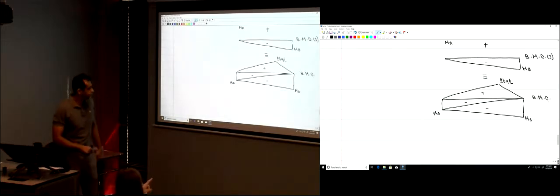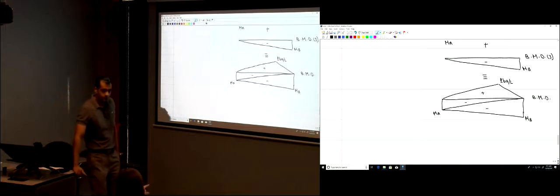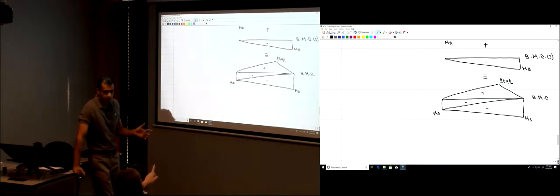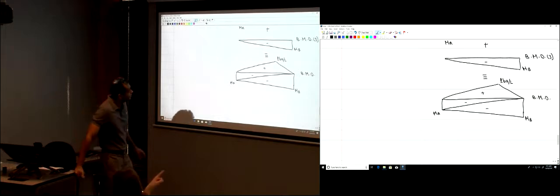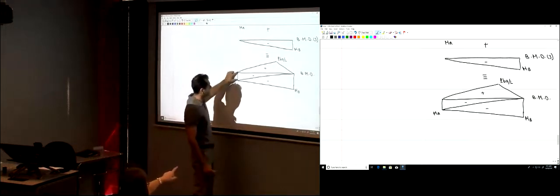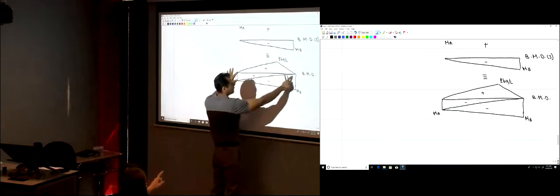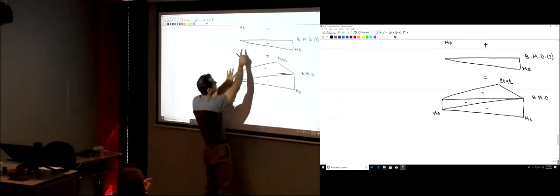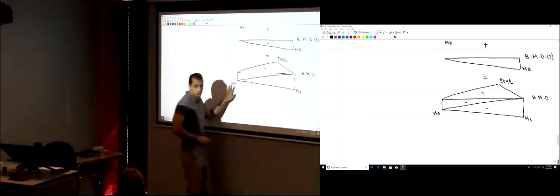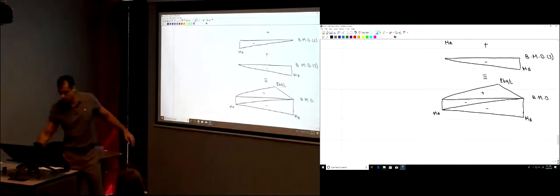So the tip for B would go to the 0 or just go to the bottom of A? Is it more than MA or less than MB? Right? That's your question? The magnitude of MB compared to the magnitude of MA. I'm saying, like the very far edge of MA comes to the 0, but the B comes to the bottom of A. So MA here, in this bending moment, it's not shown here.